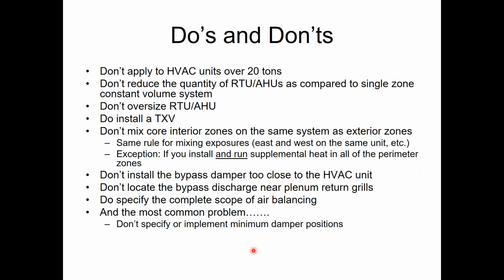All right, so let's do some quick rules of thumb here, and then I'll tell you a couple of things that have to happen on the current energy code if you want to use VVT. Right? And this is kind of stuff that I've already said, but we'll just summarize it real quick. Don't put VVT on a system above 20 tons. If you do, call me. Let's talk about it. There's probably something weird going on here.